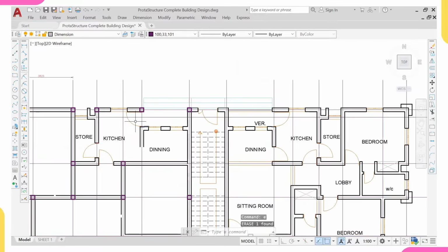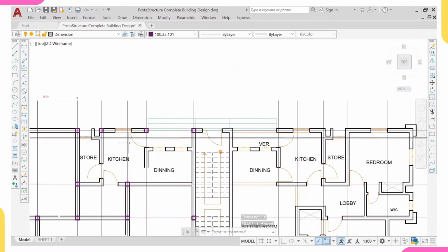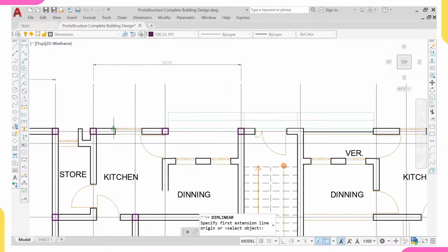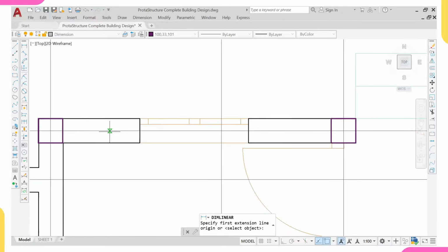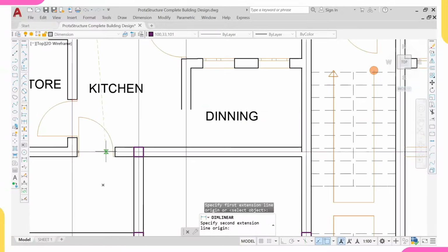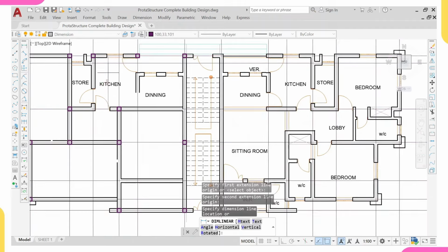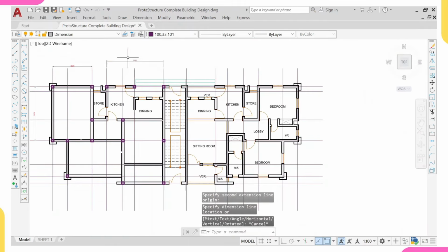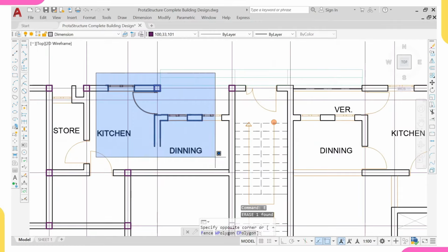So coming over to this point, I'd like to make the whole of here one panel. But let's check the dimension. Let's be sure that it's not more than 30 meters square area. From here to here, I'm having 5.5. Then I'll click on linear again. Let's check from this point to this point, I'm having 3.25. So none of them is up to 6 meters. That means it's not up to 30 meters square area. So I'll click on E, enter, delete it. That means I will have the whole of here to be my slab.